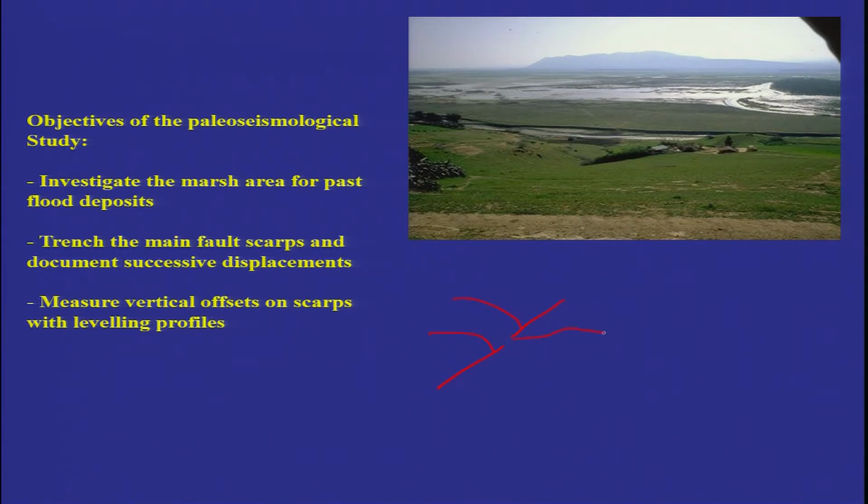Then what they were able to identify was that this channel did not cross here, and because of this warping they saw that there was flooding here. So, a ponding condition, definitely if the cumulative scarp which they saw was greater than 2 meters, because 2 meters was approximately the average displacement picked up in the 1918 earthquake. So it was more than that. The similar phenomena would have occurred in the past.